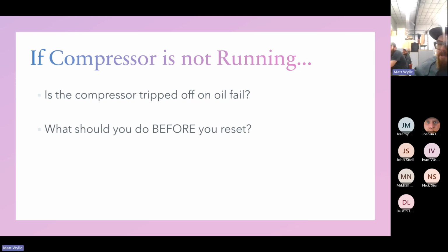Check the sight glass. Do you go and just push the button and reset it? I usually ask someone else to reset it and I hide around the corner. Make sure the oil didn't go to another compressor. Correct. I would want to make sure that there's actually oil in it before I reset it.